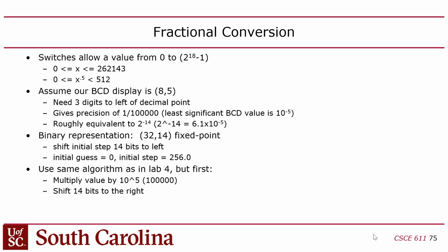And for those of you that were here last week, I did an example for the exam from chipdev.io, which used a state machine. So I'm going to go over that. Then the lecture after that is my favorite lecture, on timing analysis. How do you calculate the speed of a digital circuit? How do you calculate the clock rate? So we're going to talk about setup time and hold time and timing closure. That's what the CAD tools are doing to guarantee that your circuit will work at the clock rate that you want, right? So that's a lecture.